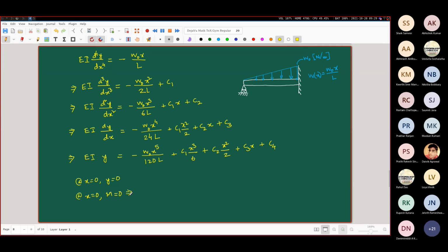And please note that unlike before, I am very much allowed to use this m equal to 0. Allowed means this m equal to 0 does give me some useful information, because the governing equation that I started out with is a fourth order differential equation. And this m equal to 0 gives me a boundary condition where the order is 2, which is definitely less than 4. So this actually gives me a useful thing. Yeah. What else?